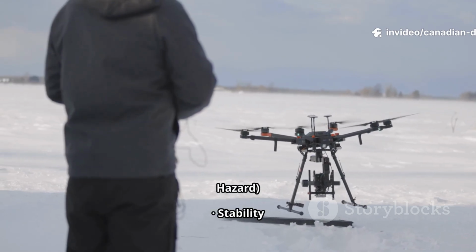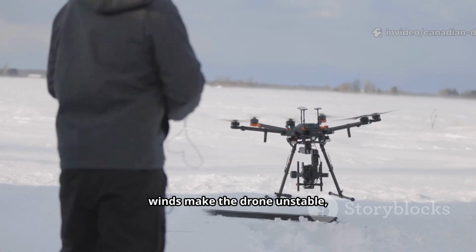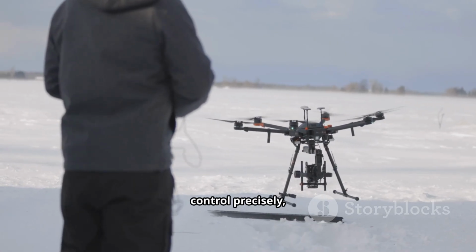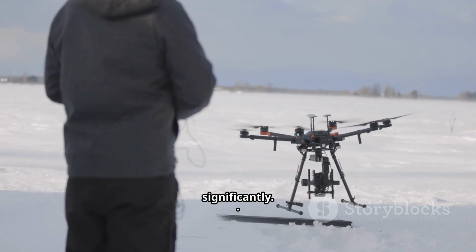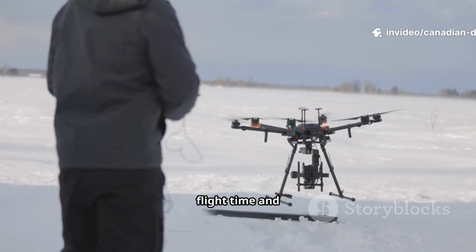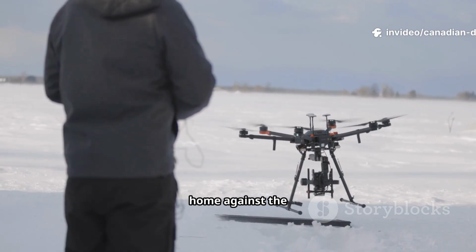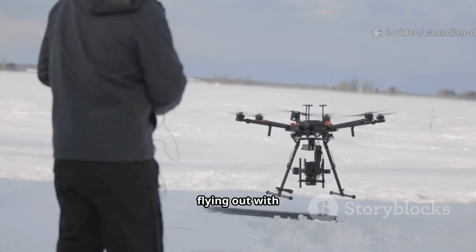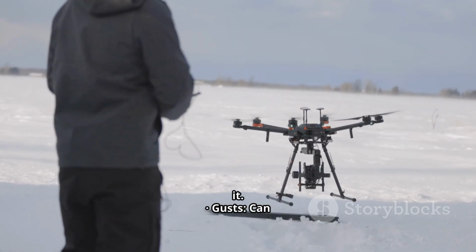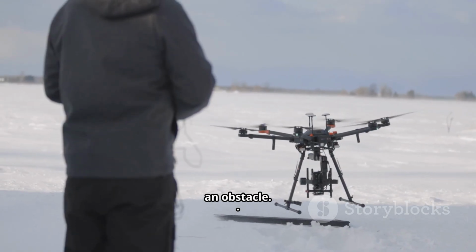A. Wind, the biggest hazard. Stability and control. High winds make the drone unstable, difficult to control precisely, and can cause it to drift significantly. Battery life. Fighting a headwind drastically reduces flight time and battery power. You will use significantly more battery returning to home against the wind than you did flying out with it. Gusts can cause sudden altitude loss or push the drone into an obstacle.